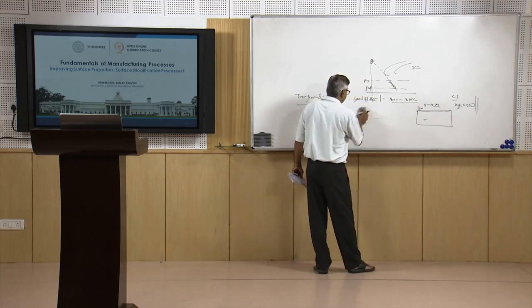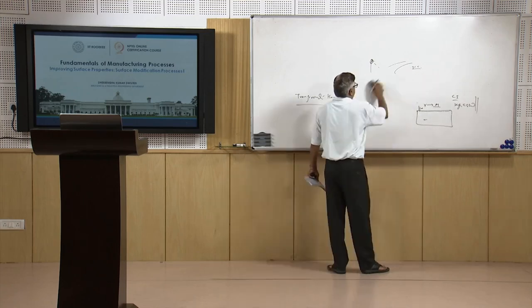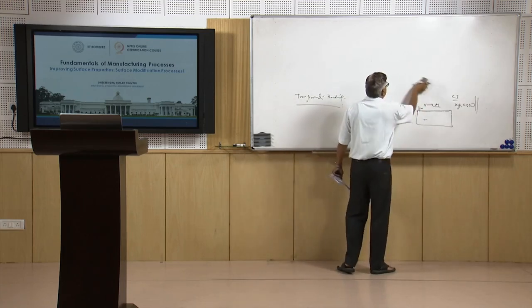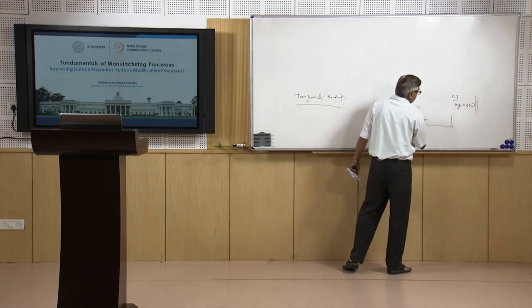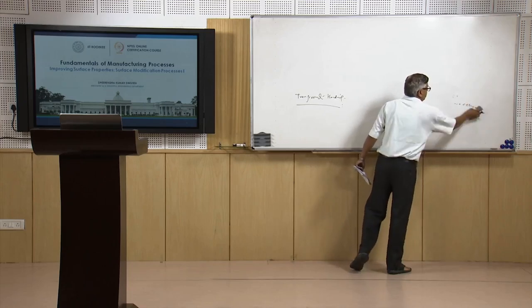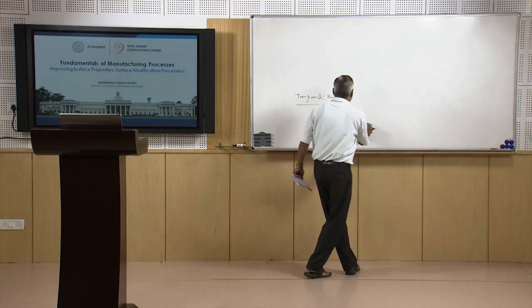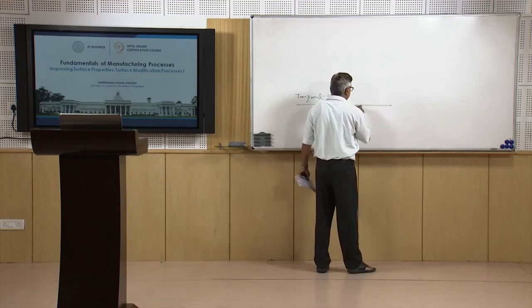So this is the basic principle of transformation hardening, wherein rapid heating to the austenitic state is followed by rapid cooling, either due to its own cooling effect or by water quenching, and the martensitic transformation is realized. In flame hardening, a lot of heat is actually fed.